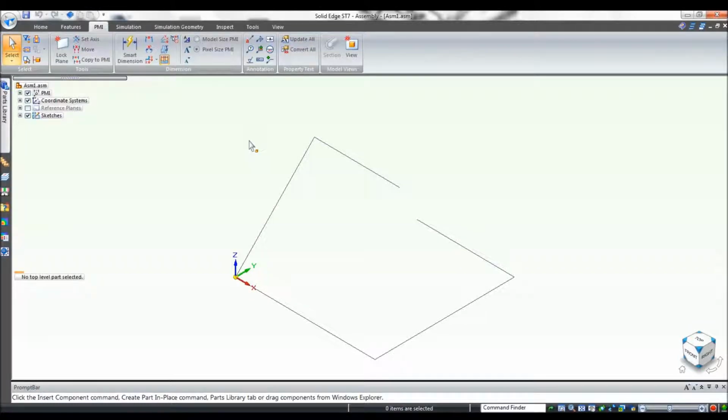So the objective of this exercise is to achieve a total calculation of the flat distances on an unbent tube. In other words, dimensions on the flats and length dimensions on the bends, no matter if they are 90 degrees or if they're 45 or at an odd angle.